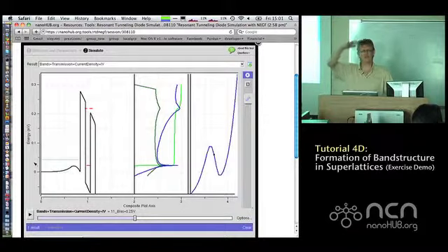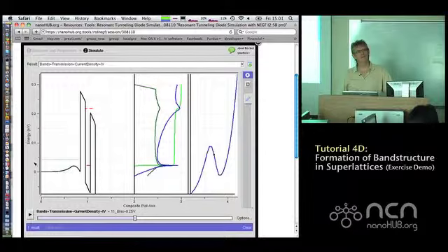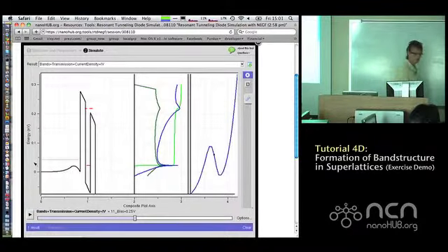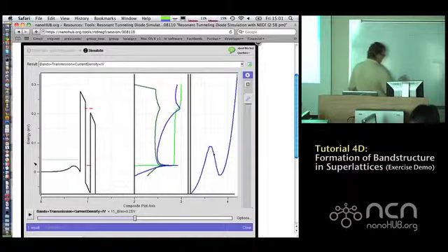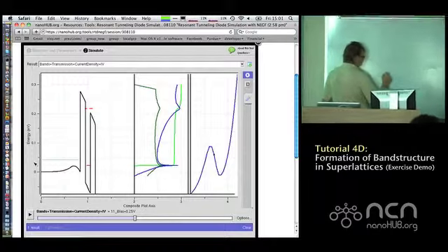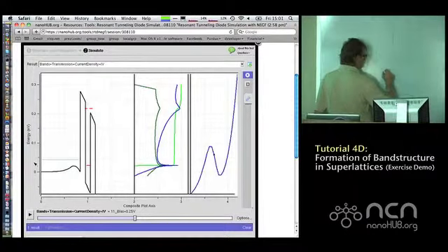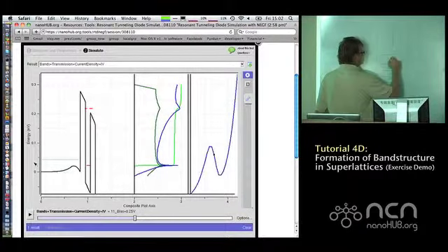Okay, this is like a layered device, a sandwich. So you have this contact metal touching the heavily doped semiconductor, right? Yeah. Well, it's like a stack. Think of it as an epitaxy stack. So you have, say, gallium arsenide, and then you dope it heavily, gallium arsenide, and then here's your barrier, aluminum arsenide, gallium arsenide, aluminum arsenide, gallium arsenide, gallium arsenide, metal.